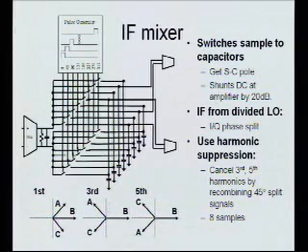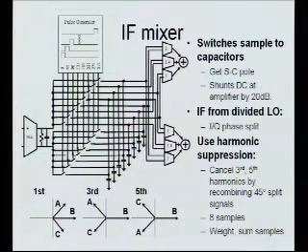And so now I'm sampling onto eight capacitors, all these different signals, and then adding them up with the appropriate weights to get the cancellation. And yes, everyone who sees this, if I don't have the progression, people just laugh when they see this. All right, well, it works.